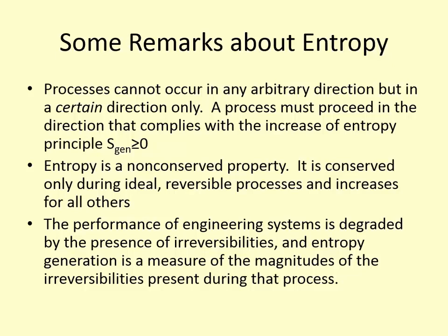And entropy is not a conserved property. So you can't recover the entropy that you've generated. You can't somehow destroy it. It's only conserved during ideal reversible processes where no entropy is generated in the first place. So in every other process that has any sort of inefficiency in it, entropy will be created. We can't create mass, we can't create energy, but we do create entropy. And the performance of engineering systems is degraded by this process of irreversibility, in that we cannot recover the energy that's lost. Once it's lost, it's gone forever, and there's no reversing that.